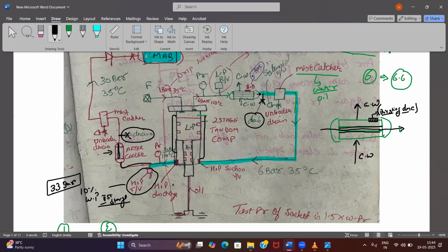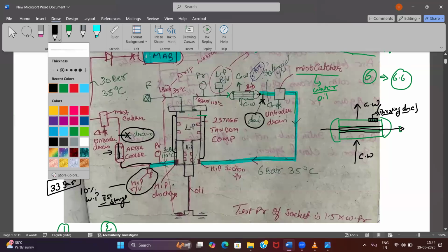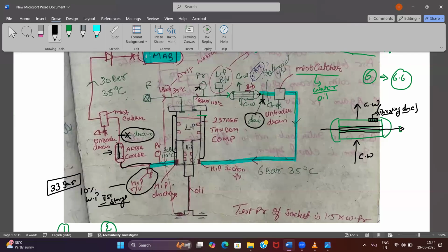First, the pressure gauge will fluctuate, no, sir? Wherever the weakest link is, that is going to burst. You are not standing in front of the main air compressor that you will come to know my pressure is fluctuating. But the gauge will fluctuate, no, sir? Obviously in this case also the gauge is going to fluctuate. If you have 4.5 bar and suddenly a small leakage starts, the fluctuation will obviously be here also. You will have loss in pressure.